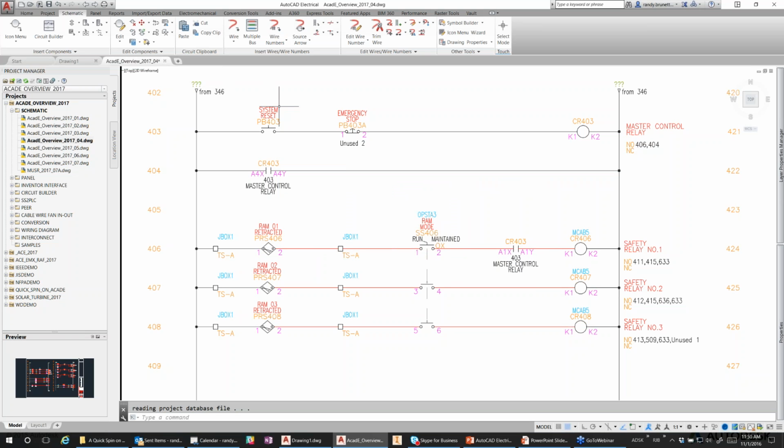A couple of other quick things I'm going to do is just add some wires. Again, this shows how quick and fast this is compared to AutoCAD. Notice I'm just selecting on the lines and it's automatically adding the connection dots. It's automatically snapping to the right places. And to take out this piece of wire, if I just hit trim wire, it trimmed that command out. So you can see I've saved several clicks over the trim or break command in AutoCAD, and it automatically removed the connecting dots for me.